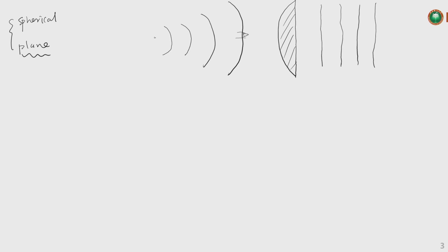So I think this is not very often used in the microwave or the military range, but for terahertz and optics, it is really used because we want to collimate the beam. Collimating the beam, right? So we want to make it collimated. Sometimes we use maybe two or three lenses to achieve that, to make the beam a plane wave. Also, the beam width is reduced, and then we would have more power or energy concentrated, to achieve a much longer propagation distance.